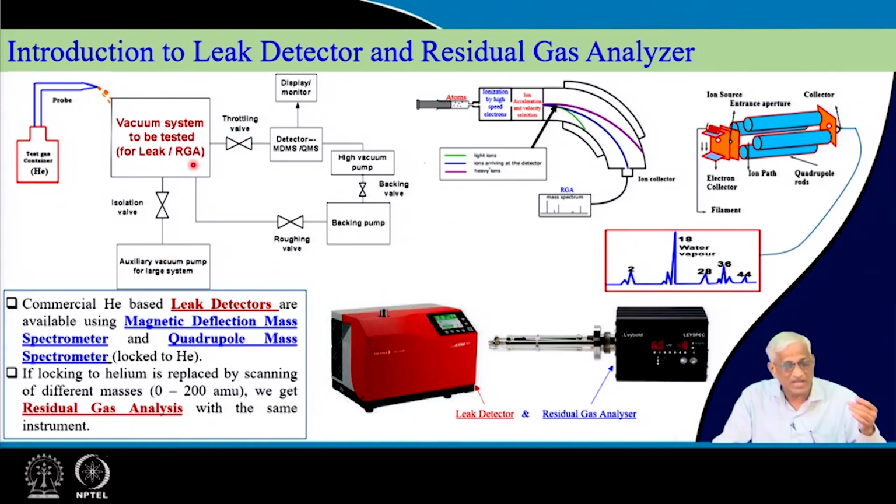Now, it is a dry thing, and from 10^-2 to 10^-5, even though it is a large system, it can be handled by these pumps, and during that time 10^-2 should be further improved to 10^-5. No need for this at leak detection time, let it be 10^-2. So, that means you close this valve, you close this valve, and if there are some more problems or heavy leaks, keep running this also, no problem. But this valve should be opened at that time, and during that time the roughing valve should be closed.